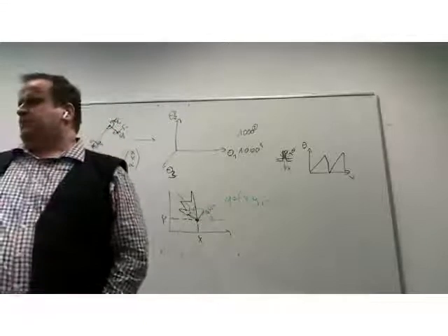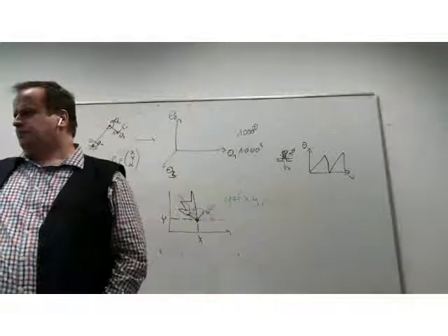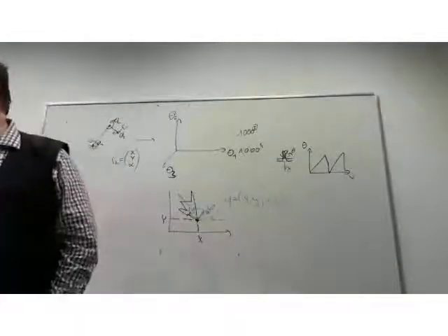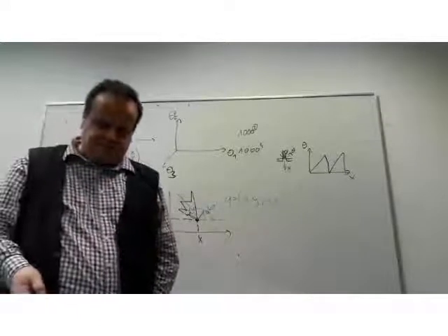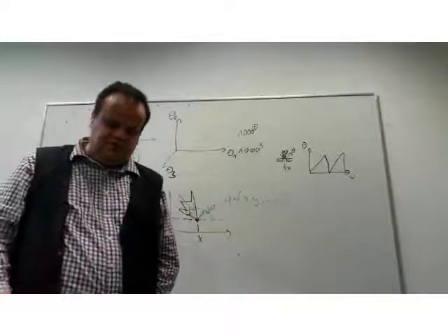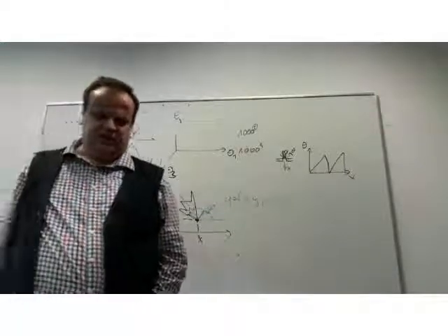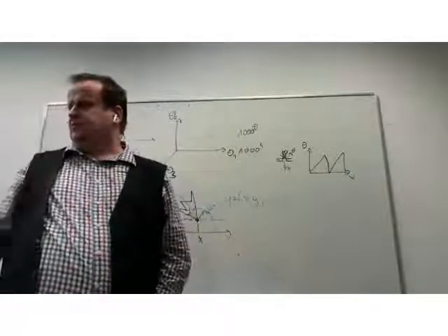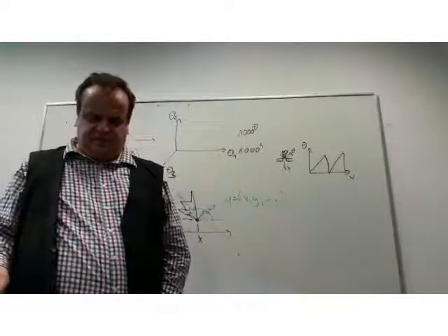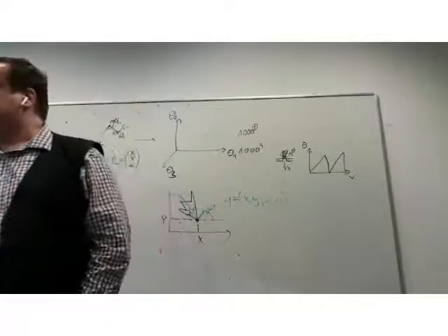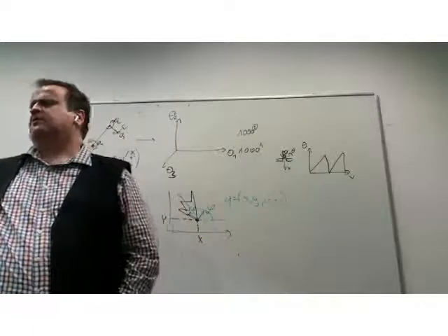If you look at workspaces, using an example robot from the side, the gray area here is the set of possible points the robot can reach. So the workspace of the robot is the shaded area. If you look from the top, the robot cannot turn 360 degrees, as you can see here. There is some limit on the angles. And this is the workspace of this specific robot.